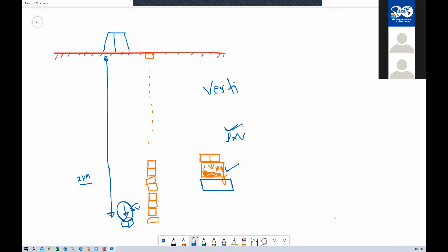Density is something you can measure; we can measure density in the wellbore with logging tools. Understood? That's why in literature you will see the overburden stress expressed as the integral of rho g delta h, starting from 0 to a depth of d. So you have to integrate the force applied by these individual elements and combine them at a given point of interest. Okay, is it clear, guys?